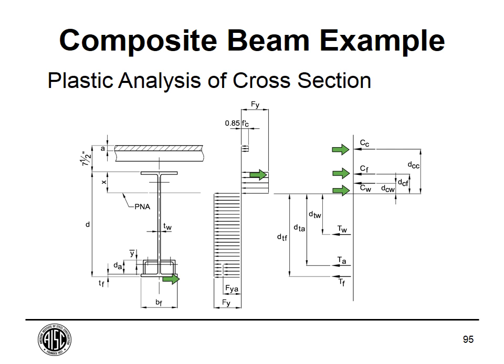So now we get on the tension side of the plastic neutral axis down here, and we have a load in the flange in tension, 50 ksi for that one. The load in the web for tension, 50 ksi. But now what about the angle? Okay, it's going to be T sub A. That's going to be based on 36 ksi yield.